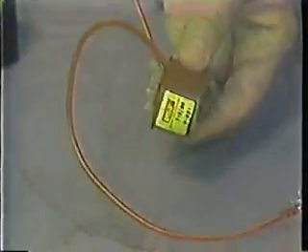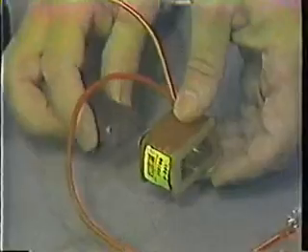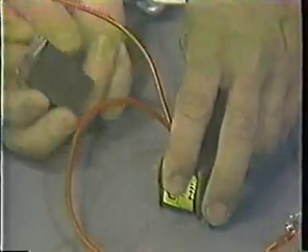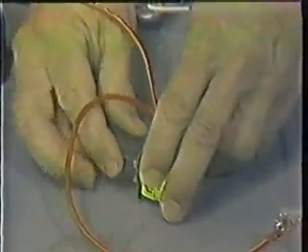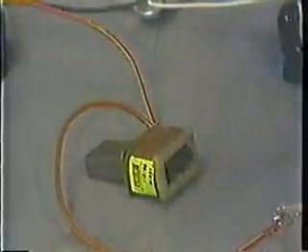Earlier, we showed how current flowing through a wire caused a magnetic field to be created. When several loops of wire are close together, their magnetic fields tend to reinforce each other and create what is sometimes referred to as a suck coil. A suck coil is the common solenoid coil like this, and the name suck coil is derived from the fact that when a piece of iron is brought near to it, the iron tends to be sucked into the coil.